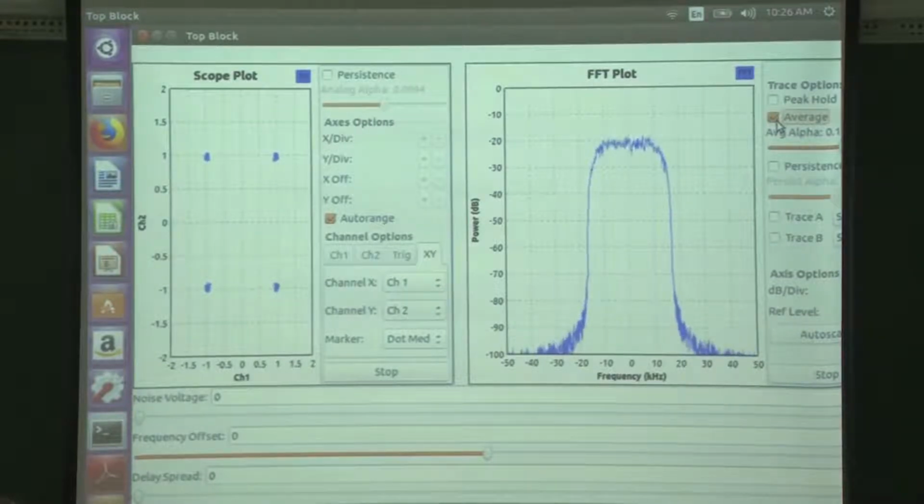Okay. So as I said, in QPSK 0 0 is one of these points, and 0 1, 1 0, 1 1 are the others. So there is a stream of signals coming through. I am looking at the receiver, to find out about the transmitter. And here is the response of the channel that I have put in the system. How does its output look? What you have to concentrate on is this minus 10 to 10 region, which is fairly flat. That essentially means that the input is coming out exactly as the output, right?